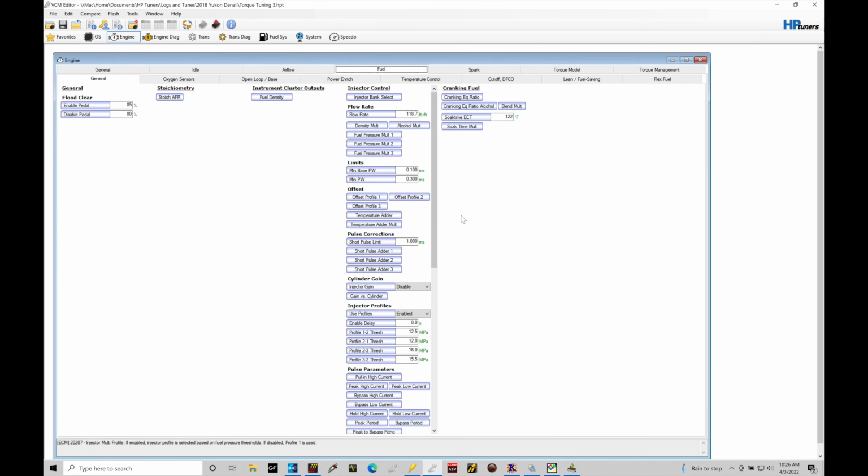Now, when we're working with the direct injection system, as I just mentioned a minute ago, we have our underlying fuel and airflow model equation. Fuel mass is equal to air mass divided by target air fuel. So for a given air mass coming into the engine, we specify a certain target air fuel. Closed loop, that's 1.0 EQ ratio, stoichiometric, or if we're in power enrichment, that's going to be a richer EQ ratio. And in that situation, it's going to have a richer target air fuel. Knowing the air mass and knowing the target air fuel, we can figure out a fuel mass.